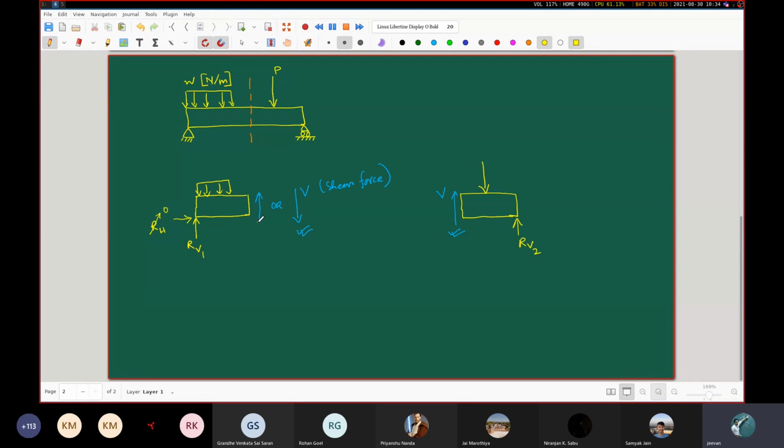So on this cross section also, on the left hand side of the cross section, you will find there will be an internal bending moment, which is represented by this kind of an arrow. And here also you will find that this is by this curved line, this curved line and this curved line. Now the convention is that you consider this anti-clockwise thing to be the bending moment for this left part, and for this right hand part you take this clockwise.